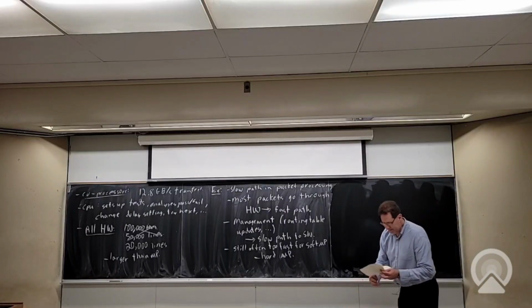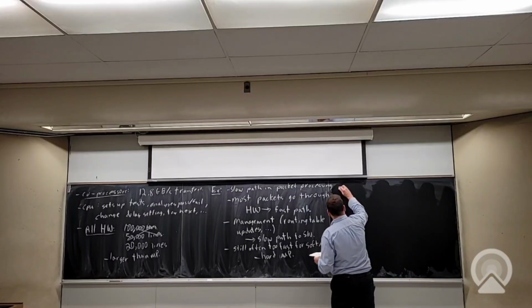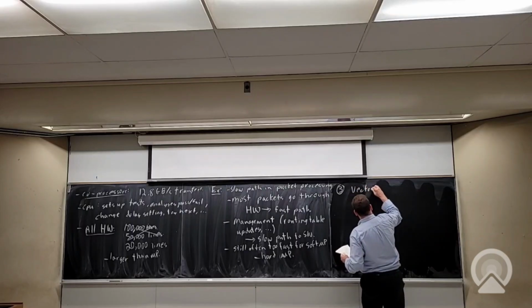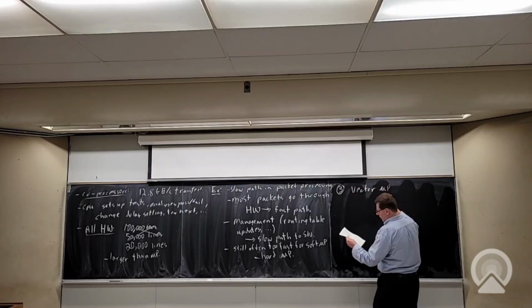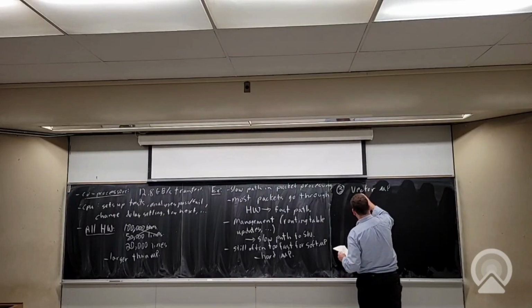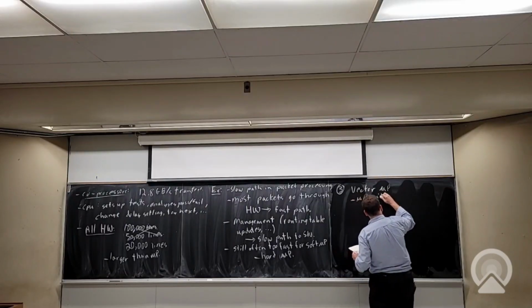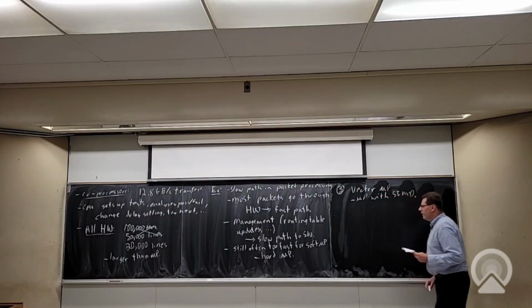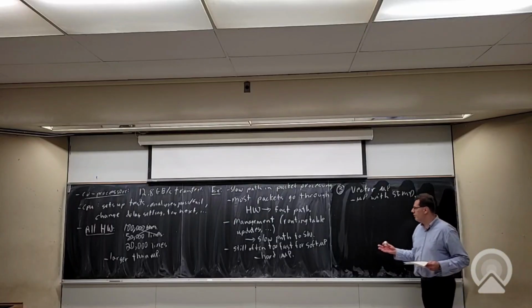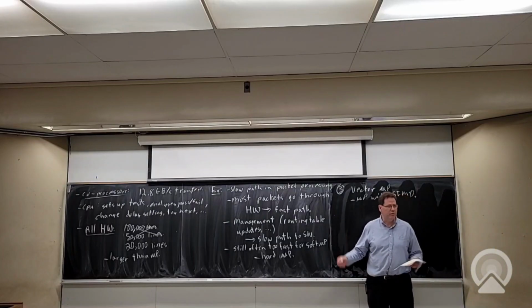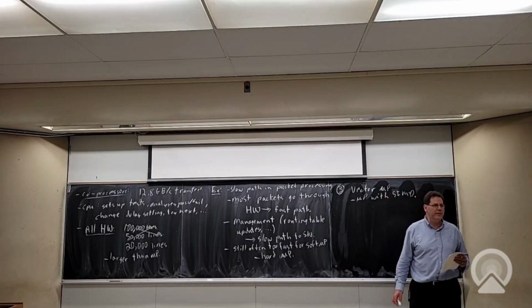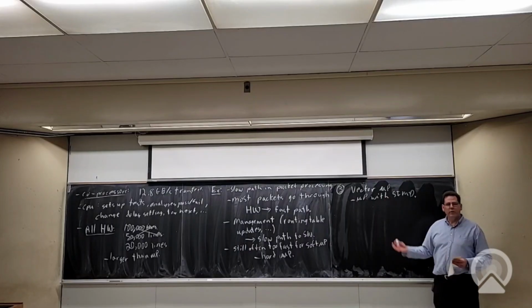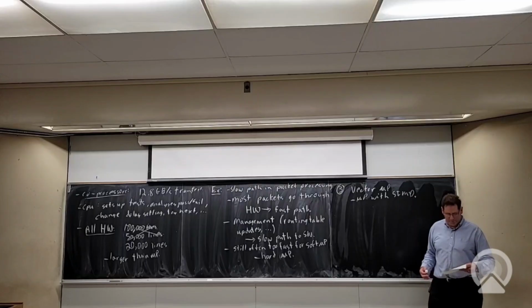All right, well, let me write that down for completeness. Okay, so you can make a vector microprocessor, which is just a microprocessor with SIMD. Okay, and nowadays, the hard processors in an FPGA would usually have that. The soft processor, you could decide whether you wanted to use it or not. If you're only using it for control paths, it's not really very useful. If you're going to do some data processing with it, then it might be useful.